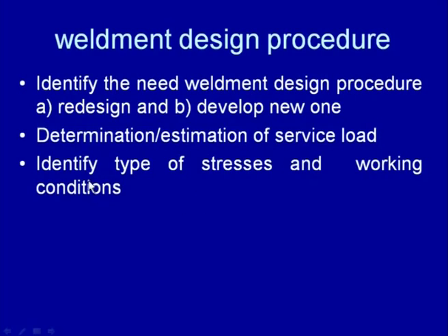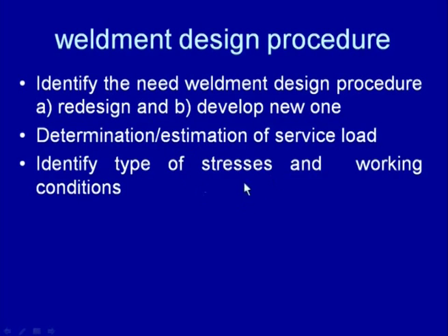Many times the data regarding the service load is available, but sometimes it is to be estimated based on experience. The second is the identification of the type of stress and the working conditions. That means what type of stresses will be acting on the weld joint during service; these may be in the form of tensile, shear, bending or torsional loads acting on the component. So, accordingly we will be using the suitable design criteria and